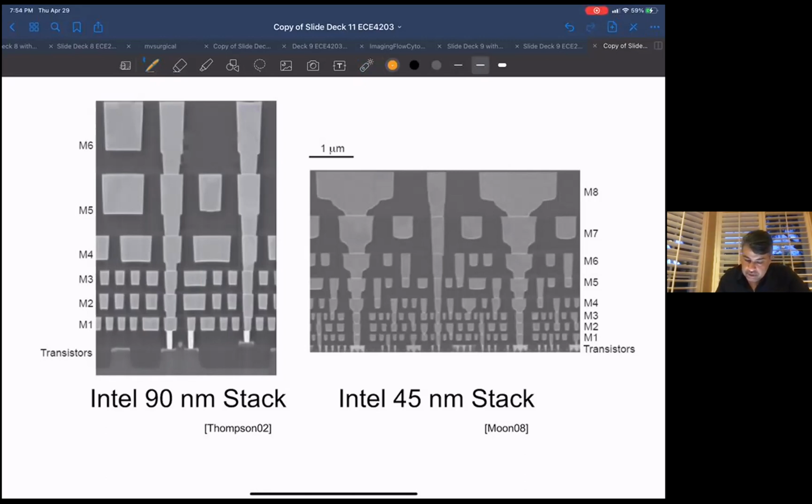So these guys you tend to have for what you'd call local interconnections, because they're dense. They tend to be dense routing, which means their feature sizes are narrow. You can cram a lot of these things there, but high capacitance, resistance. So you want to use these for local interconnections, like if you've got your logic gates in a block, you want to connect them up together, that's good.